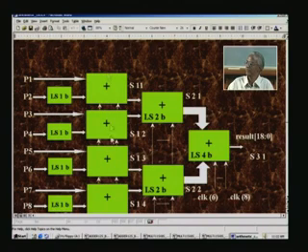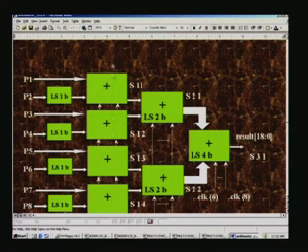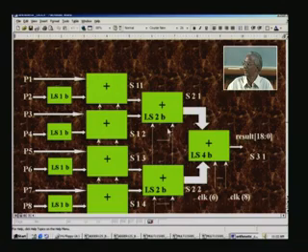So, concurrently you will have all the partial product results here, and that is what we said before, that FPGA or ASIC design is characterized by massively parallel circuits. That is what we have here, and when you see the DCT you will be astounded by the parallelism that will be built in. It is also highly pipelined, in the sense that internally there are so many pipeline registers. For example, 2 registers are hidden inside, and that is the reason why the clock has been input there, and so is the case here, 2 more here and again 2 more here.